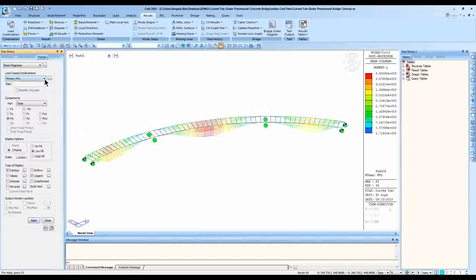And this is the envelope result. But if you're looking more for the forces, the concurrent forces, so this is a normal force. These are actually the values, that's the maximum, the worst case at every location. But if you're more interested in knowing the concurrent forces, find the location of your interest.